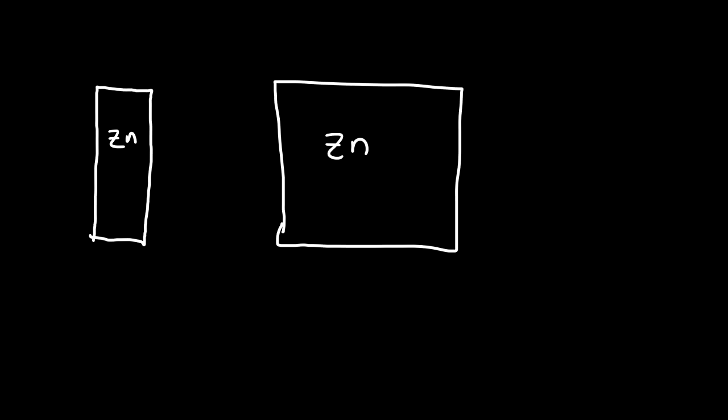The zinc electrode on the right has more surface area than the one on the left. As a result, a battery that uses this electrode will deliver more current, measured in amps, that will flow through the circuit. And so if you can increase the surface area of the electrodes, you decrease the internal resistance of the battery, and so the current delivered by the battery goes up.